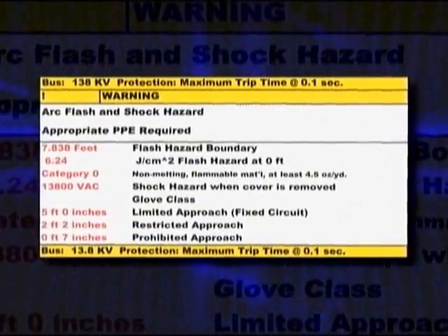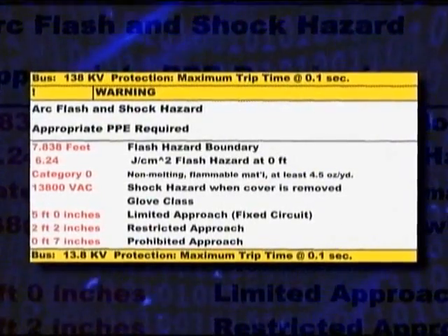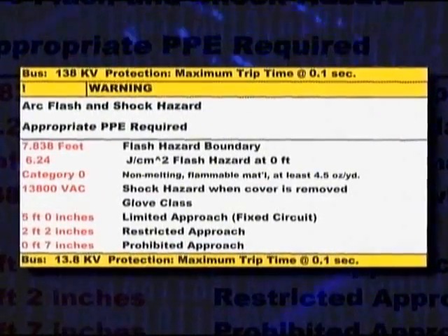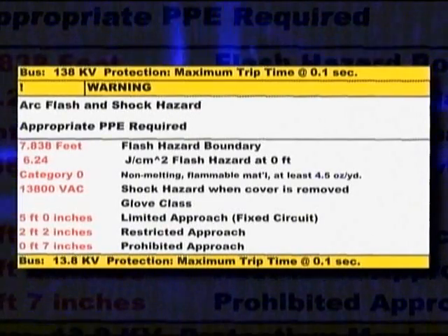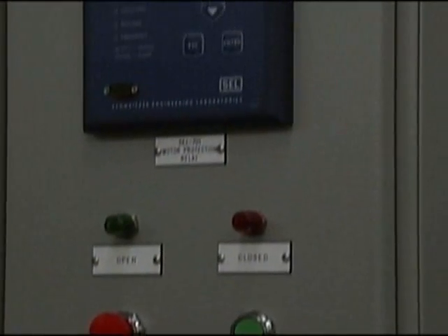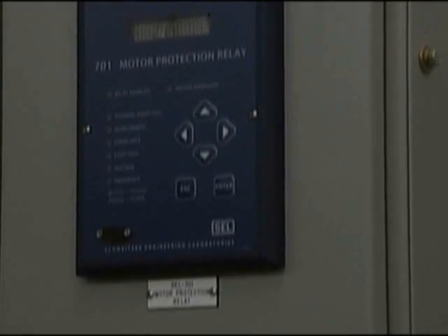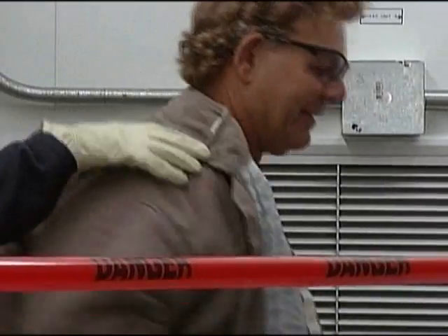Electrical apparatus enclosures and other equipment shall have the arc flash hazards clearly identified on the enclosure or equipment. However, many times the identification stickers are worn or do not exist. It is then up to the qualified person to determine the appropriate protective equipment.